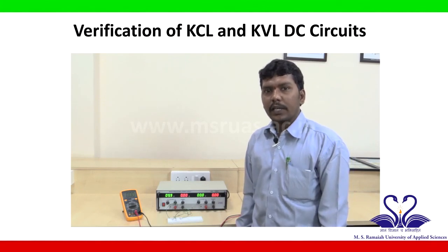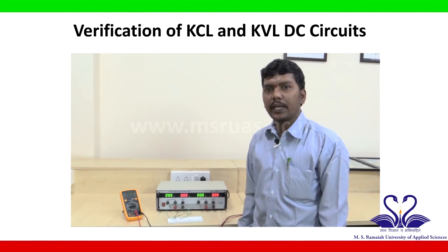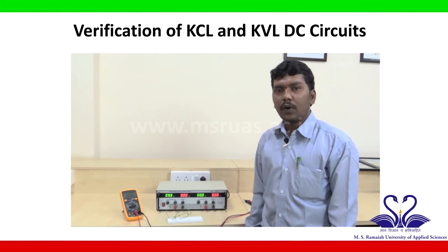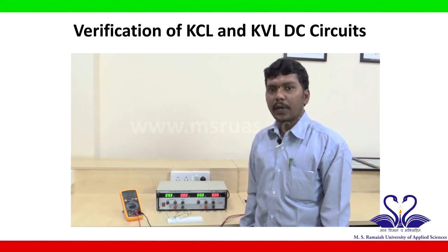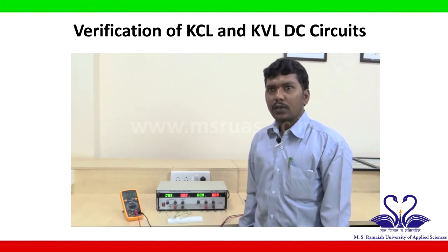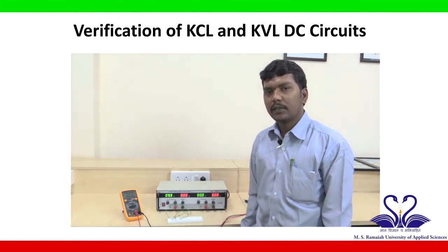So that means 10 volts is equal to the voltage drop across the resistance R1, which is obtained at 3 volts, and voltage drop across the R2 is 4.85 volts, and the voltage drop across the R3 is 2.02 volts. So 10 volts is equal to the sum of the voltage drop across the resistors R1 plus R2 plus R3. Hence the KVL is verified.